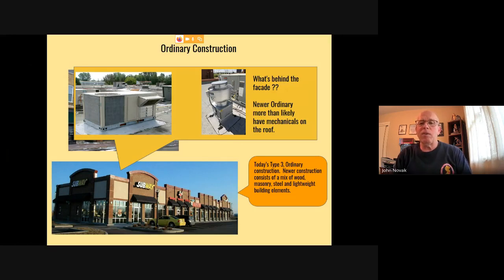And as I talked about earlier in the wood frame section, a lot of these buildings are wood truss, okay, maybe wood I-beam. So you've got substantial weight on the roof. So any significant fire up in that attic space above the drop ceiling that's compromising the structural members, you're looking at a possible collapse because these units up on the roof tend to be very heavy.